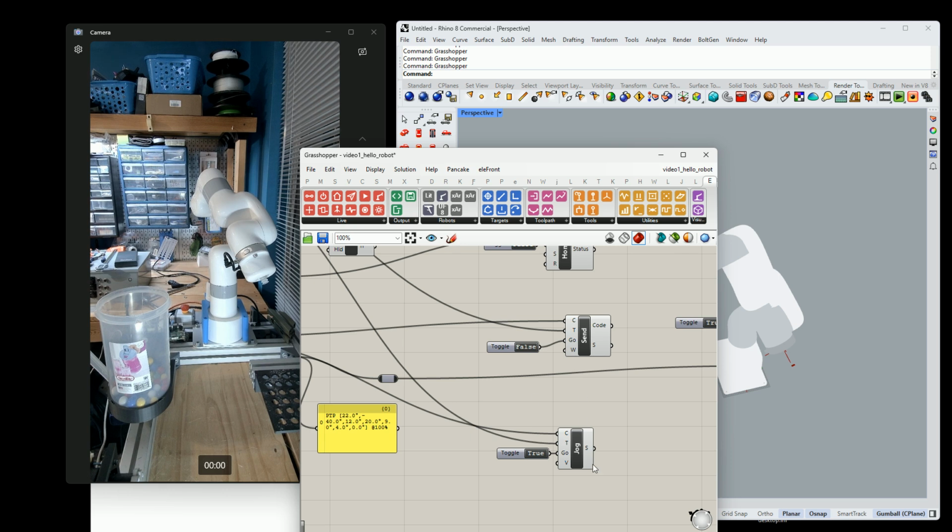What's the difference between a send and a jog? They're actually very, very similar. One just has a delay to it. We can add a wait command. So if I wanted to wait, say 5 seconds, a minute, or whatever, before it actually executes, that's what will happen. The jog does not have a wait command. So if I set send to 0, it's going to act the same.